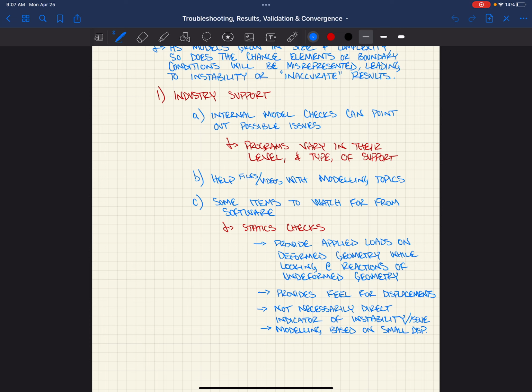All right. But in this results view, as long as you don't click anything on this results side on the project manager, there's a section that says static check. Okay? It goes through and it checks in each load case the applied forces in which direction, global direction here.